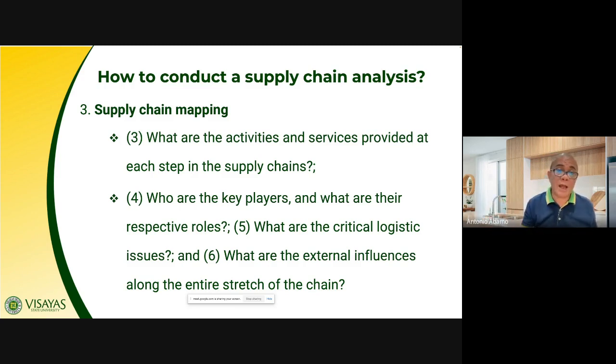Because, for example, abaca, that is either for pulp or for cordage, or it could be for handicraft. The cordage is used for shipping, for tying up at the pier, or very importantly, it is in demand for oil drilling platforms. Abaca is used there because on metal, it does not slip, it does not slide. If nylon is used, it slides easily. But abaca grips, so abaca is preferred as the material.